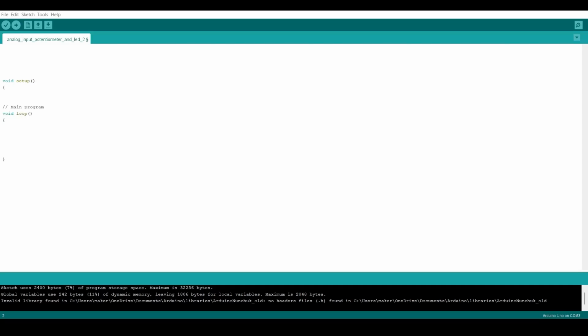There it is, guys. So now we are on the Arduino IDE, and this is where we're going to start by creating the code. Let me get started with the analog input. Let's put int, and I'm going to call it potentiometer, pot, equal. I put it on A3. So A3. That should be it.